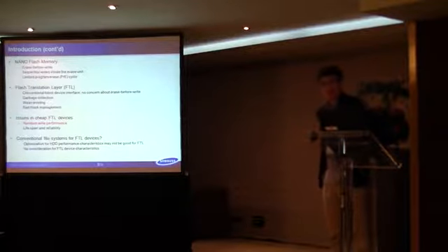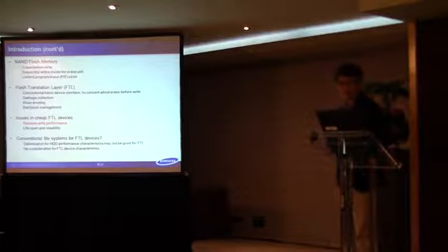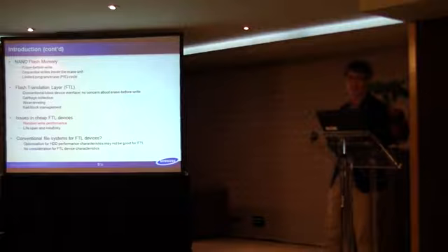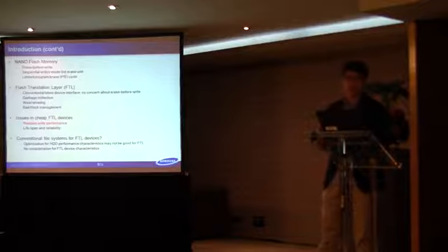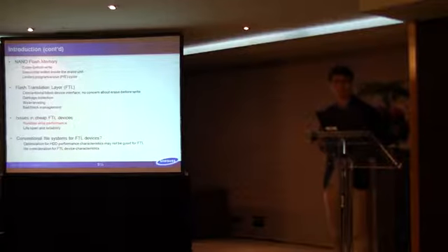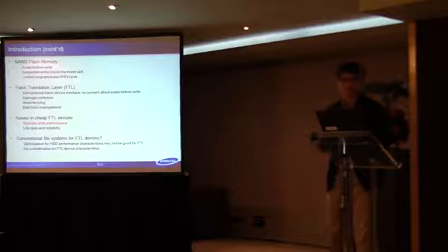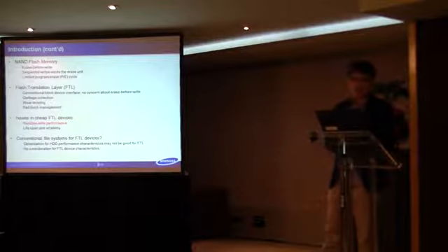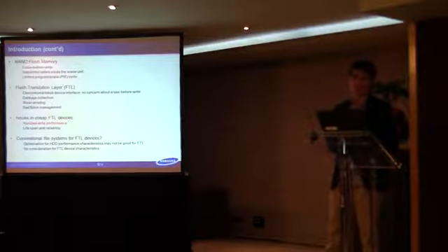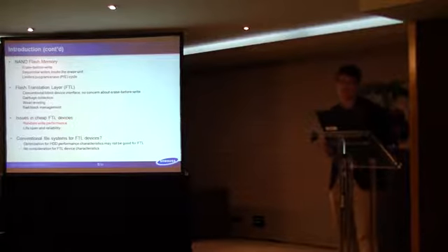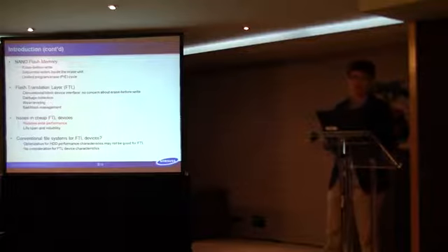So these are the flash issues in the storage. NAND flash is very different from hard disk drives. A hard disk can be written without erase, but flash memory is different. It has to be erased before writing. And this causes many problems in software design, but we have a couple of file systems for NAND flash memory, like JFFS2 or UBIFS.